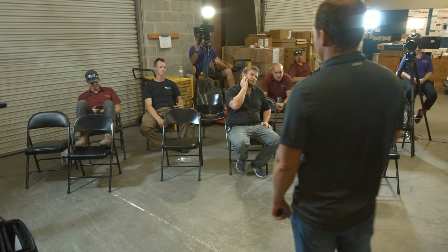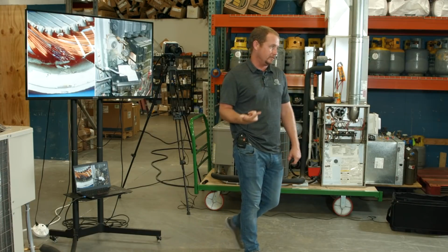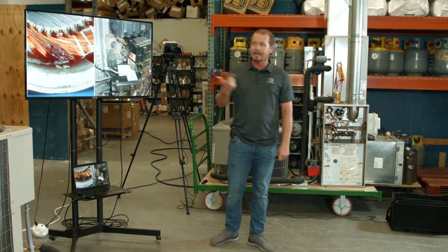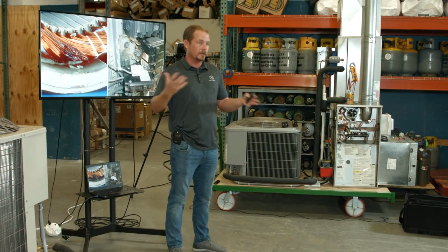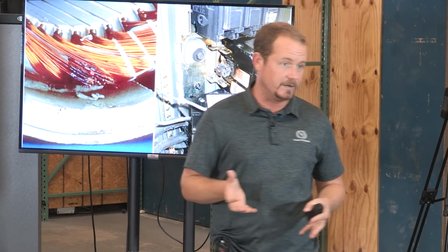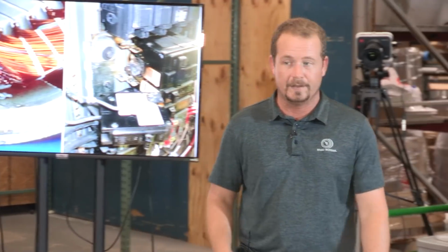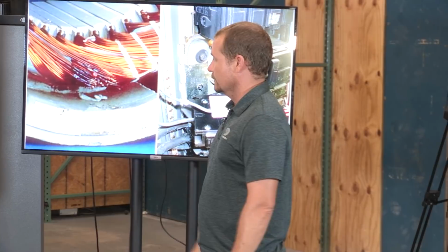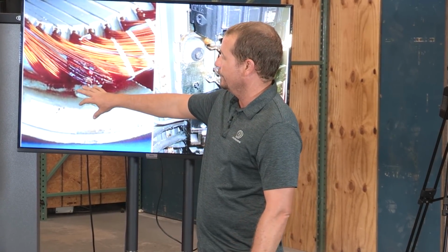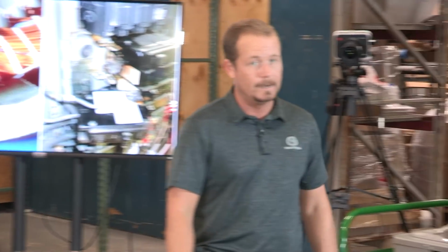So in many cases, mechanical problems cause electrical problems. Right? In many cases, that's what's going on, especially inside of a compressor where everything's in there, and something goes wrong, and now it starts bouncing around. Maybe it loses its suspension, or maybe there are metal particles that have gotten in there. That can compromise that lacquer, and then that results in that. But it could be the other way around too. I mean, it's possible. It's possible that there was just a really high current event or something like that. But again, even then, it's compromising the lacquer first. That's what's happening first.